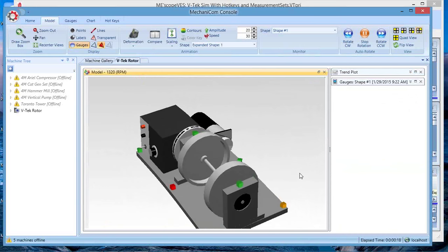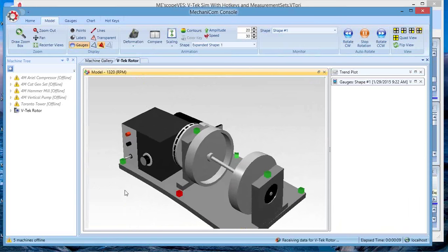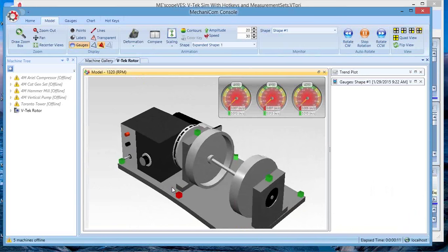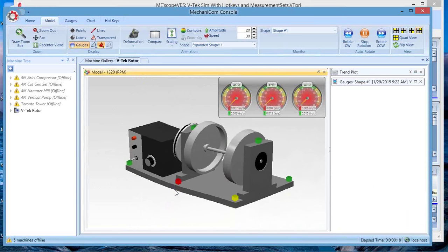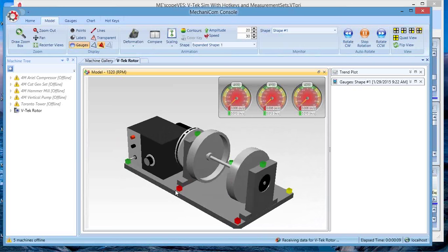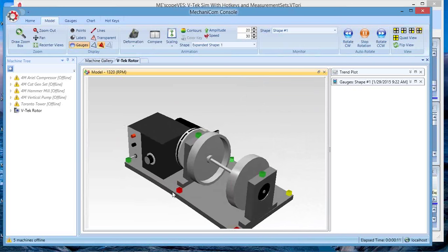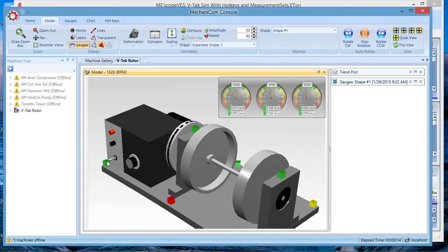But here is very similar to what you're used to seeing, an animated ODS using data from the 8 accelerometers and then expanding the ODS using mode shapes. And think of this as a curve fit. We're curve fitting mode shapes to the ODS data that's actually been acquired.